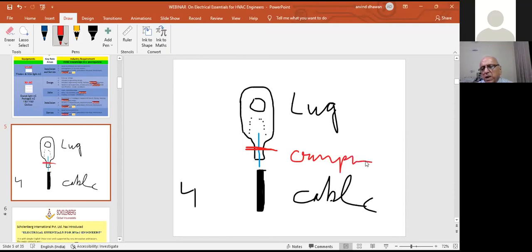It is called crimping. You have a special tool, and when you put the aluminum conductor inside the lug, we compress it mechanically for crimping. When you crimp it, the lug has a hole, right? Through this hole, we connect to the switch. All of our switches have nut bolt connections. The switch bolt will come here, and we'll put a nut here and fix it.